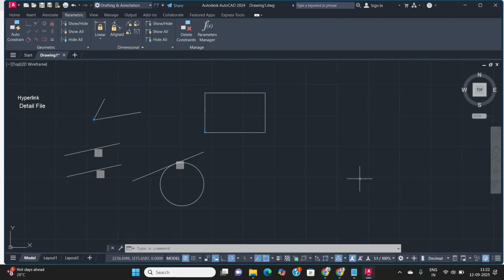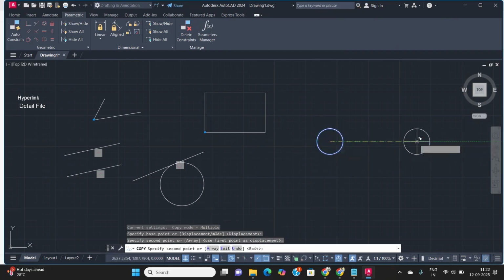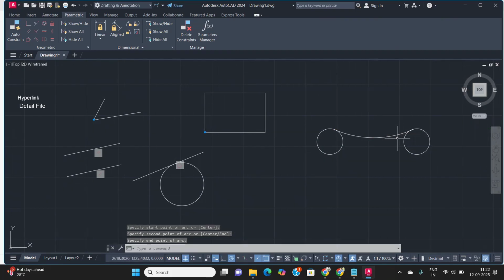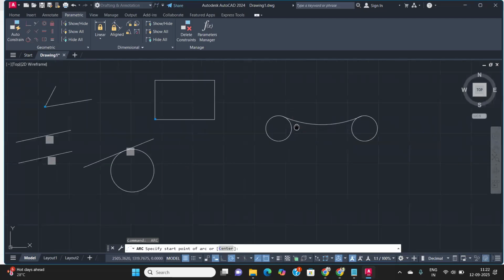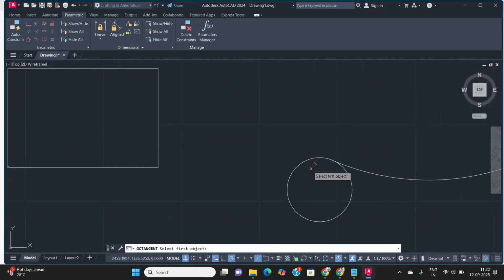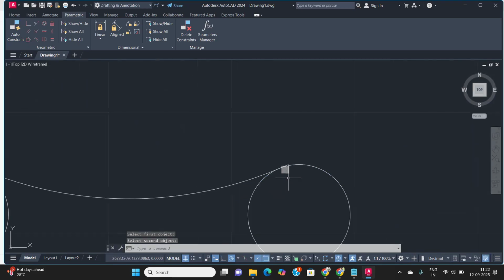So sometimes this happens when I create something. I take one example and make it here, and then I select any point, anywhere, right? And then I want to make this line a tangent at this point. For this purpose, you can use tangent, and first select this circle, then second select this point, right? At first this does not look like a tangent, just select here, select this object and this object, then your tangent will be made, right?